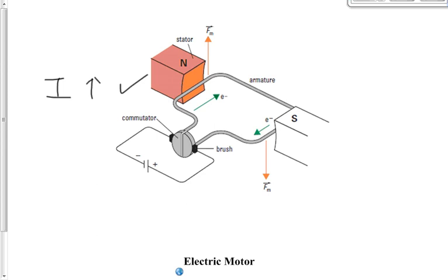What else? Yep. The length of the wire. Now be careful with that one. It's this length of the wire that matters, right? And this length of the wire that matters, not this length of the wire. So L matters, bigger length, okay, bigger force on it. Now, how would we increase the length of the wire? You could make the magnets wider, right, so that the wire goes like this. But what you probably end up doing, because the motor at some point just becomes too unmanageably big, you probably end up doing it this way.